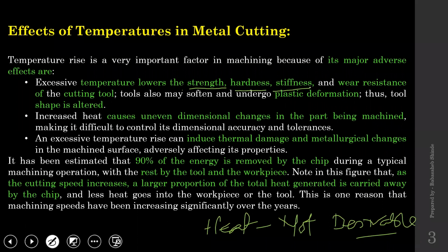Additionally, it decreases wear resistance also. So when you select a cutting tool, you think of these properties, that the tool should have enough strength, it should have enough hardness, it should be stiff enough, and it should have better wear properties, right?